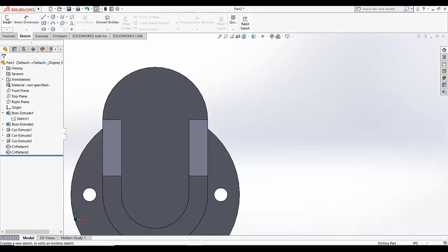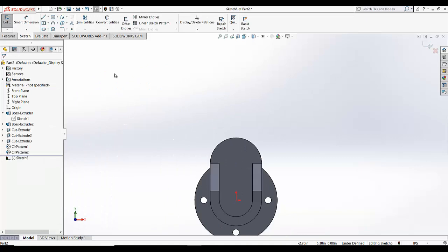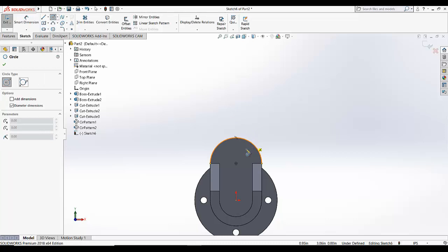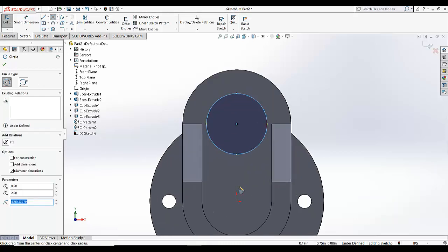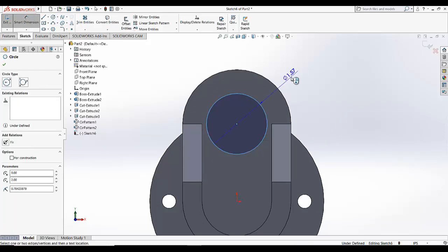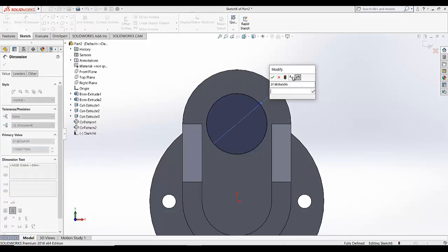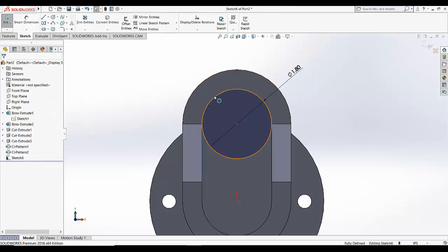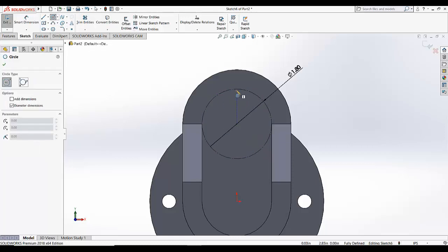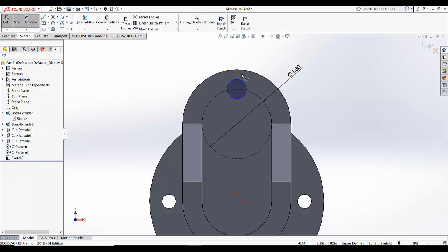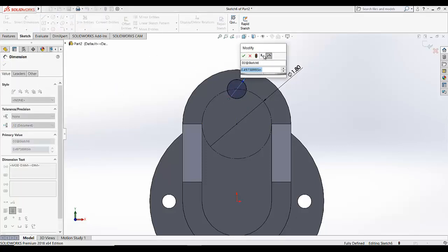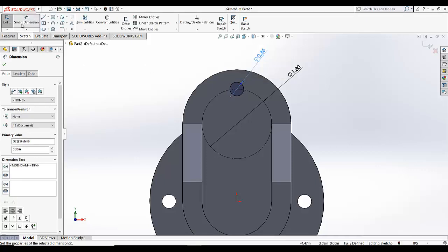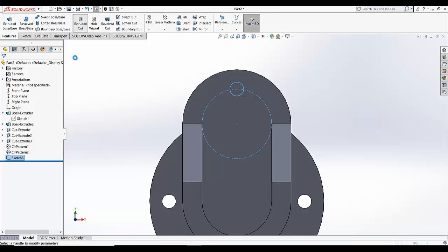And again I am going to select this sketch on this face, and then again draw a circle. When you go here, this center will be activated. Draw a circle here. This is a reference circle, and the dimension of this circle is given as 0.90 multiplied by 2 to make it diameter, and then select this circle and make it for construction. This is just for reference, and add a circle here, and the dimension of this circle is given as 0.36. Cut it.